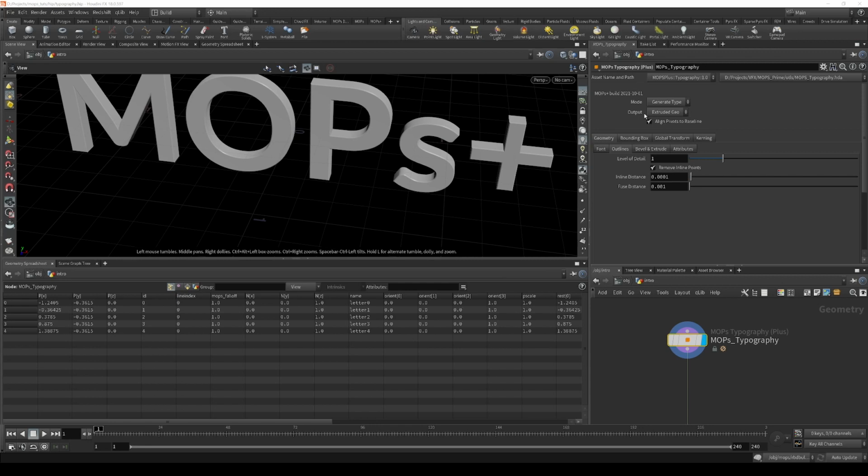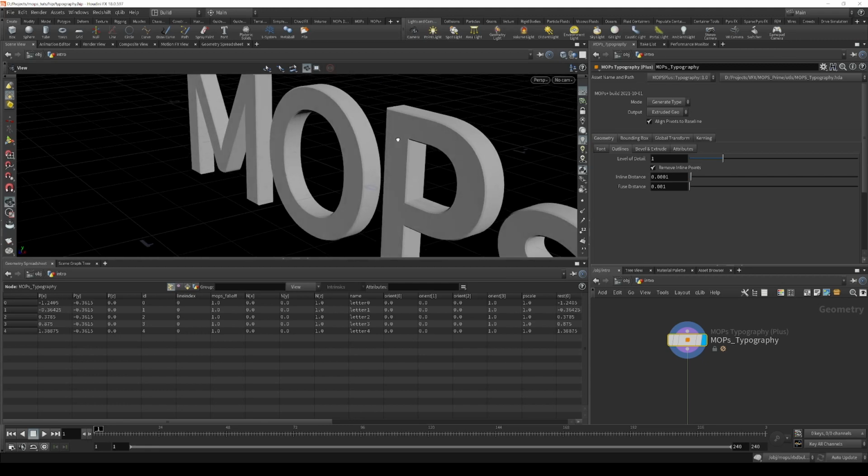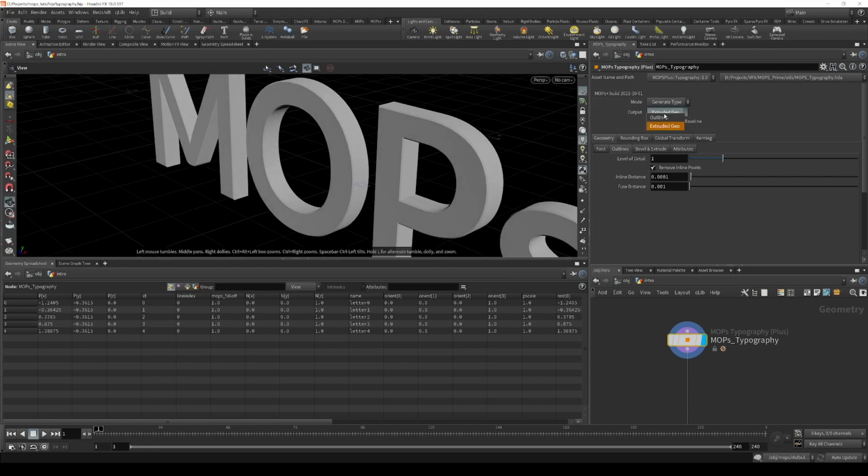The reason for the output mode is that you might not always want solid letter forms. You might not always want bevels, whatever. So the option is there in case that's what you want, although most of the time you are going to want these to be solid forms. But the more important reason is that outlines are much faster. And so if you're doing anything to this type, like adjusting the outline detail, or if you are doing word wrapping or adjusting the bounding box, things like that, those operations can be much, much faster if you are doing them on the outlines. We'll get to that point in a second, but keep in mind this output mode for when you're trying to do things that don't behave very well interactively.